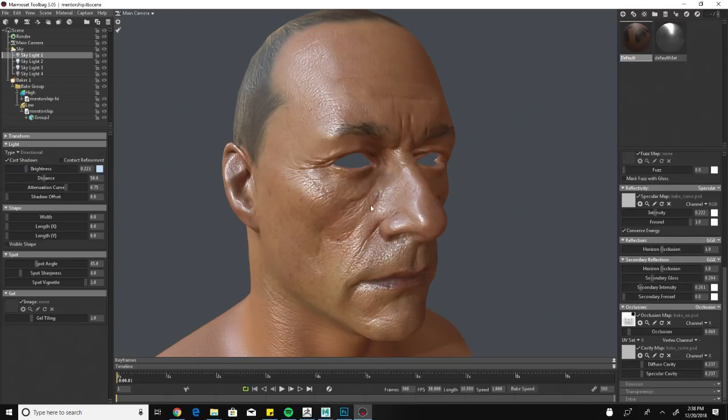but that's a little more for when you've got the eyes and other parts and things like that. Okay, another thing I like to do is immediately come into the shape, and I like to increase the width in all my lights. It just changes the effect and softens things. So I'll go in there and set it for all of these, and then I'll come back through and start to adjust brightness.